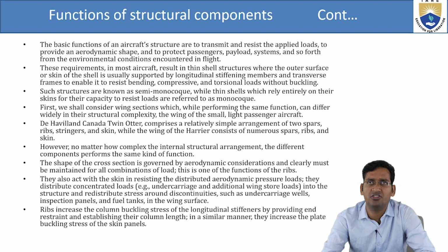Next is the function of structure components. The basic functions of aircraft structure are to transmit and resist the applied load, to provide an aerodynamic shape, and to protect passengers, payload, systems and so forth from the environmental conditions encountered in flight.